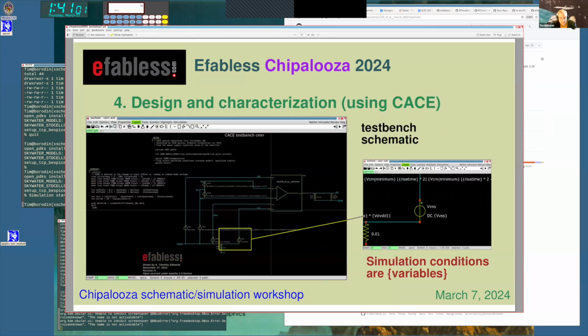Before I go do something live with this, let me just show you. So the test bench will look something like this. Again, I flipped to another test bench here, which is for CMRR, but all the test benches look more or less the same. The test benches are about as simple as you can get. You don't want anything particularly complicated, just to simulate PSRR, CMRR, or input offset voltage. The main difference between this and the test bench I was using before in my working directory is I have gone through and replaced lots of values with variables.